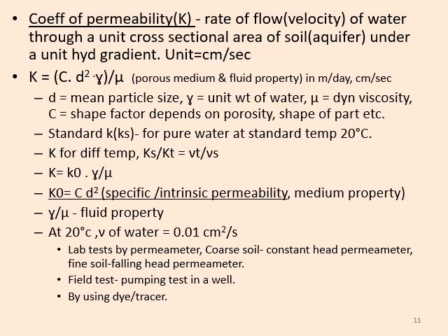By lab test, by permeameter, constant head permeameter for coarse soil and falling head permeameter for fine soil, we can estimate the coefficient of permeability K. Also by field tests like pumping test in a well, or by using dye or tracer content, we can estimate the coefficient of permeability K for a particular aquifer zone.